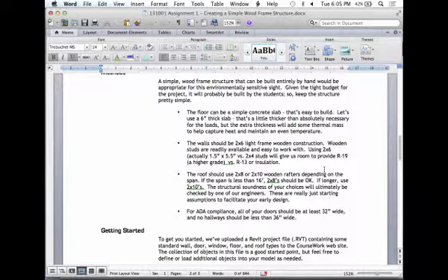Okay, so we're going to put some walls in here. And what we'll typically do with a structure like this is place the walls so that the studs of the walls, those 2x4s or those 2x6s, come right so they're perfectly aligned to the edge of the concrete. In what we're going to talk about in building modeling technology, this will be the core of the wall, the structural core of the wall, and we're going to try and get it to align so the outside face of the core is aligned with the floor, basically.